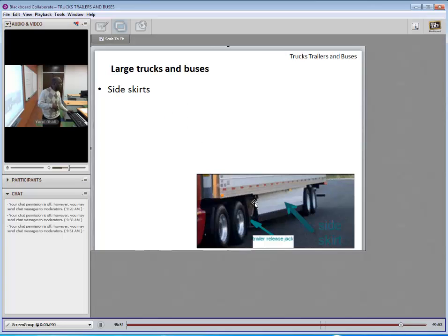In many of these designs, the side skirt starts from where you have the trailer jack. If the aerodynamic dictate were to be followed, this would inhibit access to the trailer jack, and that would create its own problems. So I suppose for practical reasons, the width of the side skirt from here to the other end is slightly less than it is at the back side.